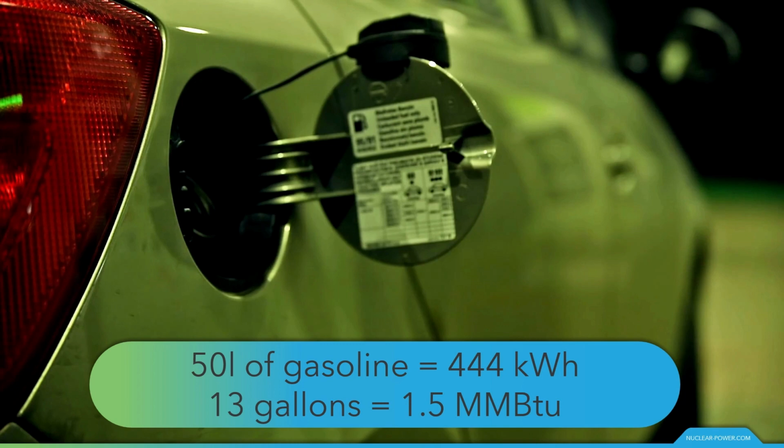Please note that a typical gasoline automotive engine operates at around 25% of thermal efficiency. About 75% is rejected as waste heat without being converted into useful work, which means work delivered to wheels. This inefficiency is caused predominantly by the second law of thermodynamics.